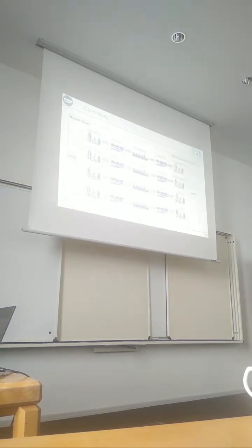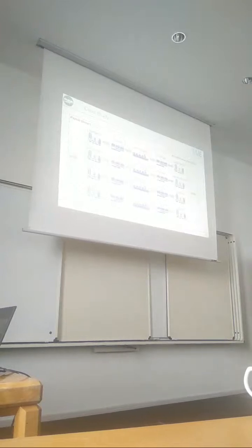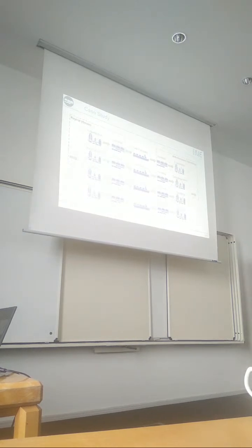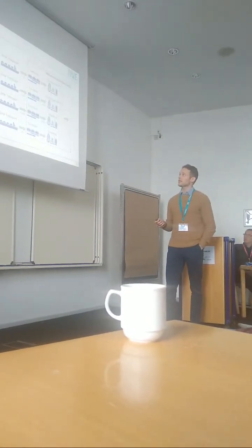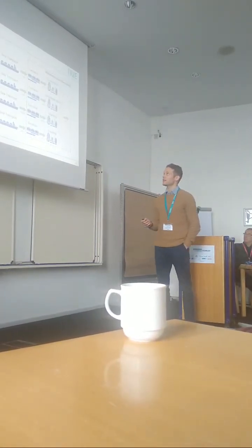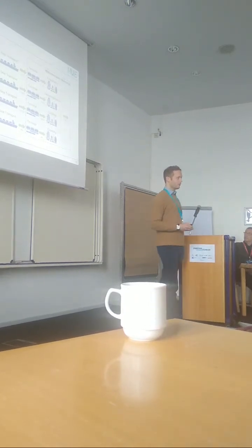Okay, so far so good. In our assessment of the hydrogen transportation from Oman to Germany, we now consider these 4 carriers: liquid hydrogen, LOHC, in this case benzene-toluene, or toluene in English, ammonia, and methanol. And we always have the same frame conditions. We start with compressed gaseous hydrogen at a pressure level of 100 bar in Oman, in the Red Sea, and we come out again with compressed gaseous hydrogen in Germany, in Wilhelmshaven.